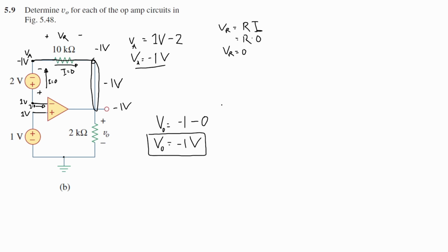So, we have solved the problem. And if you have any questions, please let me know. So, hindi pala natin ma-apply pala dito yung voltage divider kasi wala naman palang current dito. Tapos, iba yung current na dumadaloy dito. So, we have I1 and I2. So, buti na lang napansin natin na same branch pala siya ng input, yung feedback nito. That means, wala siyang current, and walang current, we can ignore this resistor.